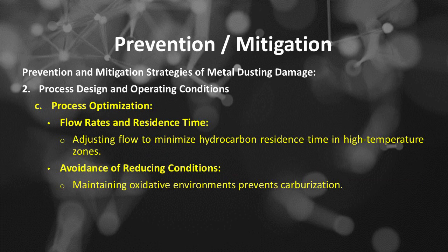Number C of the process design and operating conditions is process optimization. The first is flow rates and residence time, adjusting flow to minimize hydrocarbon residence time in high temperature zones. The second, avoidance of reducing conditions, maintaining oxidative environments prevents carburization.